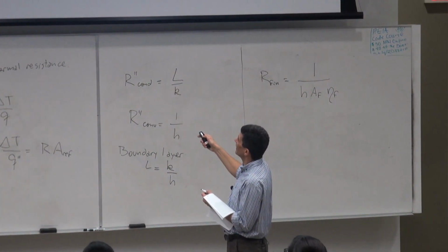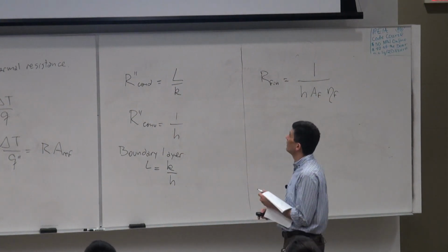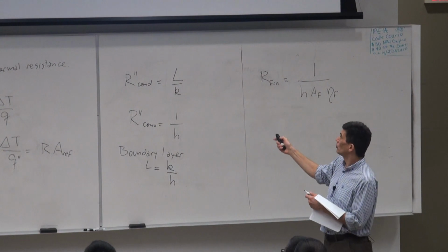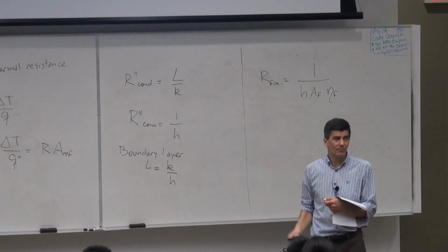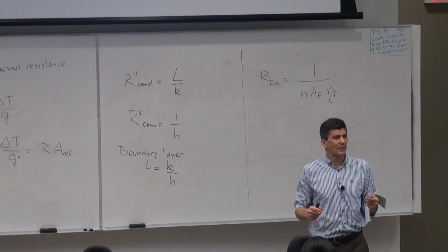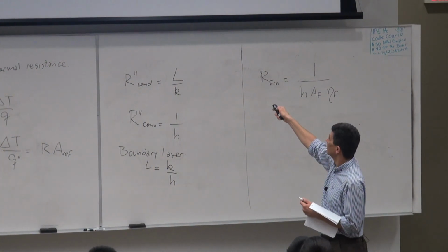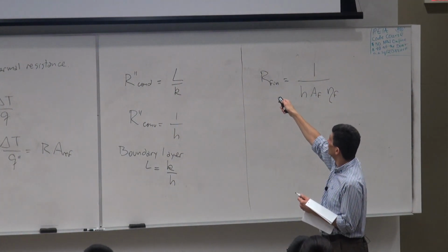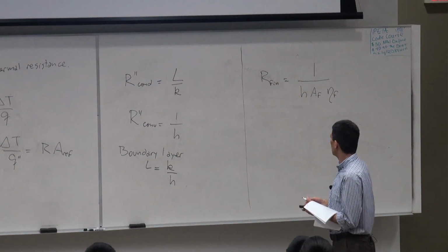What if it is parabolic? What if it is a rectangular fin? What if it is a circular fin around the tube? This is the typical case of many heat exchangers, right? For example, some AC systems, you're going to see that they have this tube with these fins around. Here you calculate the efficiency based on this parameter, which is just by looking at the figure.